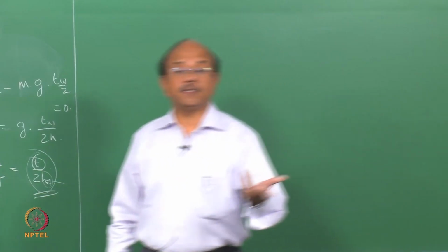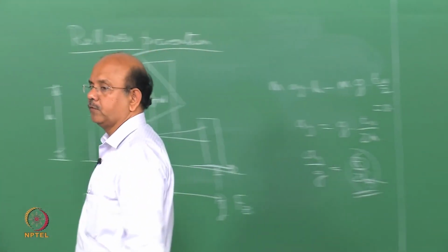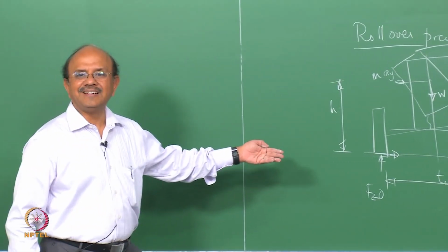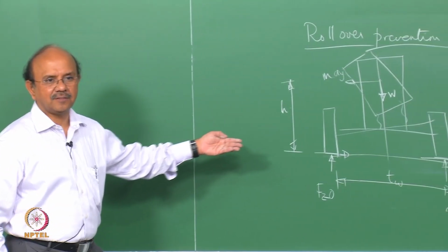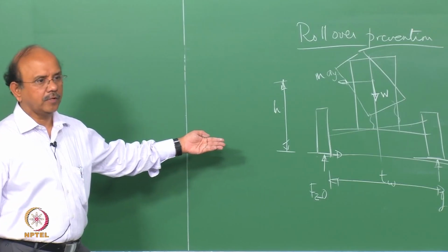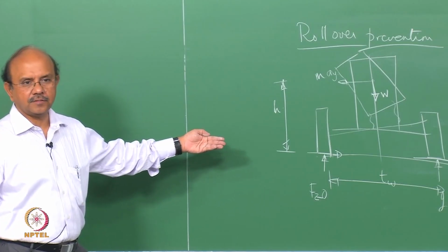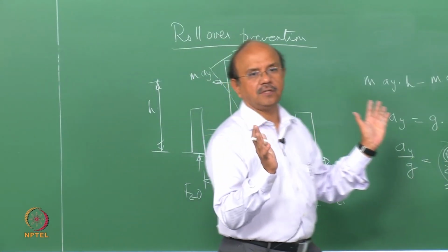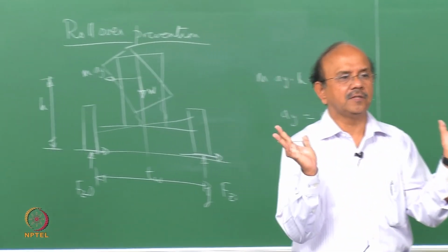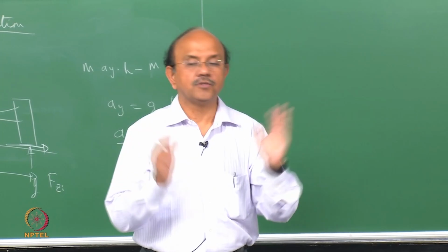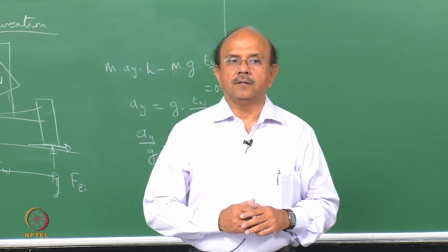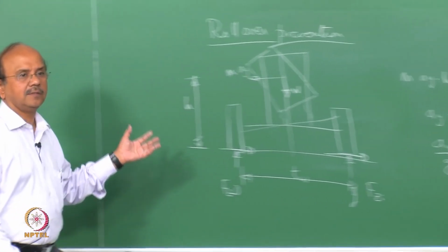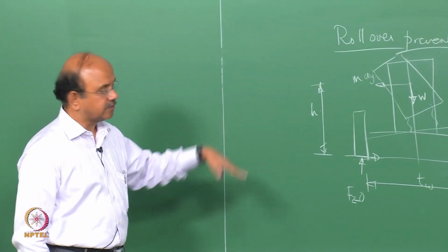For example, even without going into the details of kinematics and compliance, it is affected straight away by the tire lateral stiffness. It's affected by the camber, by the camber change, and so on. It's even affected by the torque that is produced due to the gyroscopic effects.